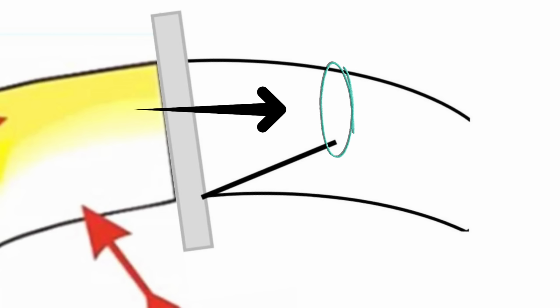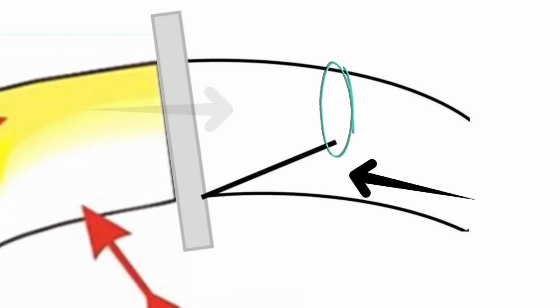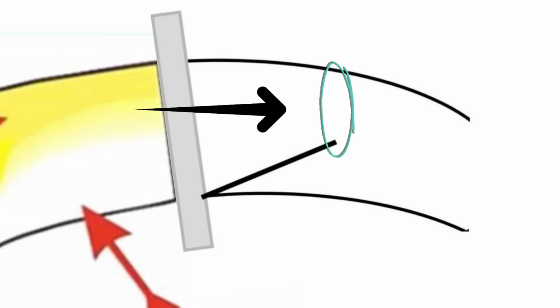You'll notice where I've circled it, there will be a high speed area because all the exhaust is going to go through that area. Now, as I said, we lift that anti-reversion dam just enough so that it doesn't quite impede the flow. So flow going out of the cylinder is unaffected, but anything that wants to flow back, that's usually along the bottom of the pipe, runs into that air dam plate and can't go back further than that, and it can't go in the opening because the flow is too fast there.